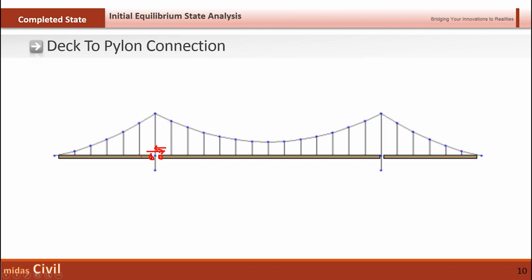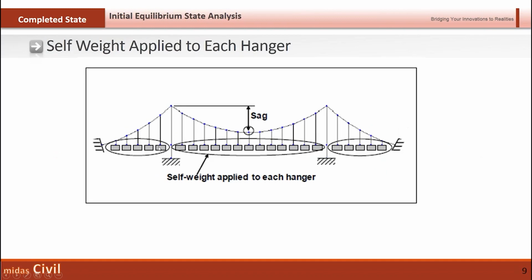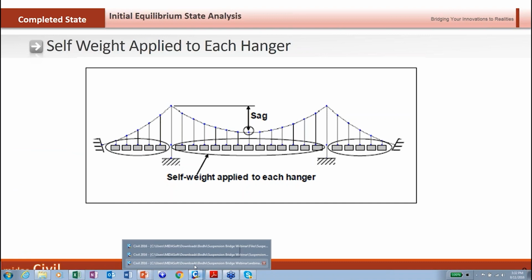Okay. Also, currently the model, because this is again a model to get the initial forces, we are just optimizing the model. So again, our point of interest will be to give loading in such a way. For such a type of loading, I have to again simulate the deck connections in such a way that the decks will not be connected to each other, the deck portions. So I have to give the beam end releases in such a way for the deck elements also. Okay, so I will go back to the model.